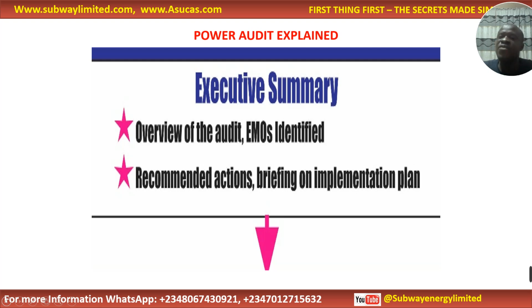That is the overview. When you go there, most times he will be telling you, and during the conversation you might ask him, sir, what do you want to power? You mention AC, fridge, 3 ACs, and all those things. And you ask him, sir, please, what is your budget? When he mentions his budget, you will know exactly whether he will be able to run those electrical loads. Because as a professional, when somebody tells you the electrical load that he or she is going to use, you will have a rough estimate, without going for a power audit.